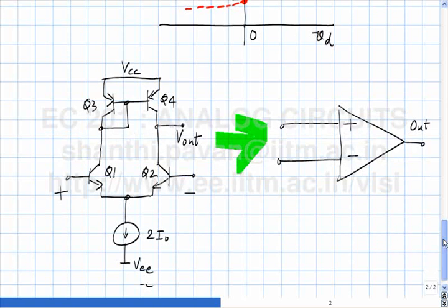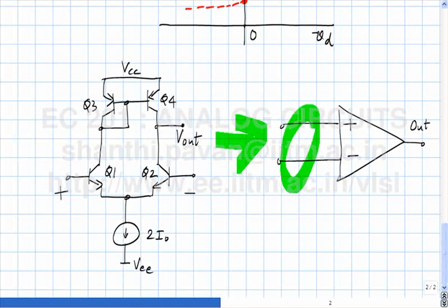That we understand, that when we sell the op-amp, we will tell the user, look, the common mode of those 2 input terminals must be within the common mode range, which is dependent on VCC and VEE. If you fool around there and expect the op-amp to work, tough luck. You should assume a reasonably intelligent user, not a donkey.